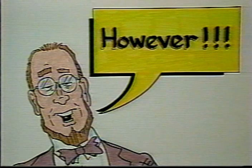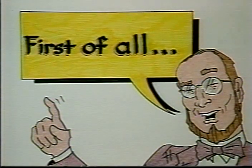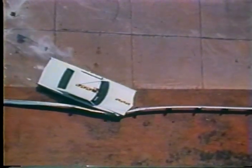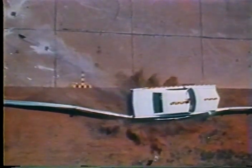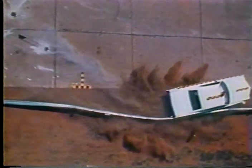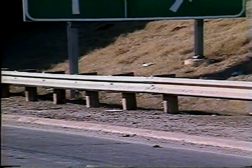However, this program will help you understand why these systems were developed, how they work, and what can prevent them from working as they were designed. First, let's review the major functions of the two systems. W-beam strong post systems are semi-flexible traffic barriers that are designed to stop, slow, or redirect any vehicle that hits them. The barriers are made up of three basic parts: an end treatment, a standard section, and a transition section. All three components are required to make up a system.